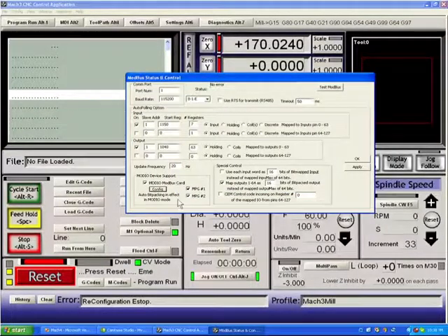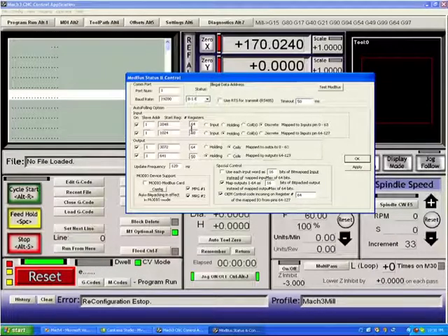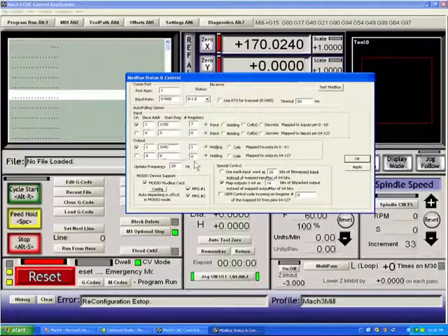For general ModBus, you do not have to use this. You would simply uncheck it, and once you uncheck it, you can see all the numbers switched to numbers that are typical for a DL5 from Automation Direct. But again, for you to use all these values, you'll have to find the appropriate memory registers within your ModBus device. And when I switch it back, it becomes again pre-configured for Peter Homan's board.